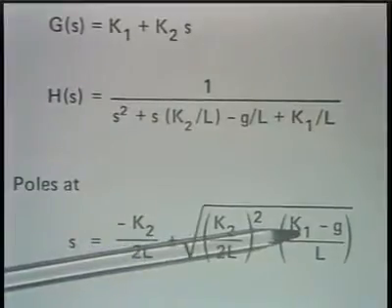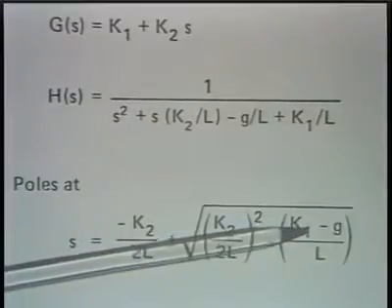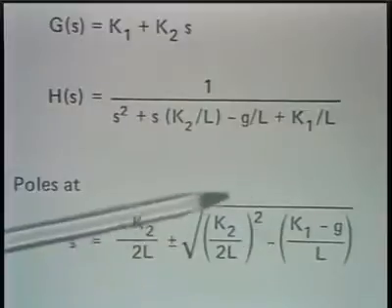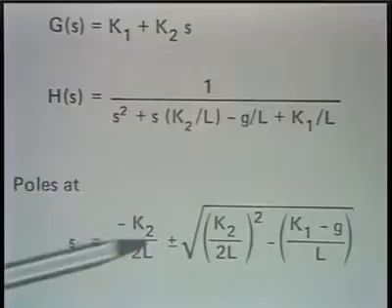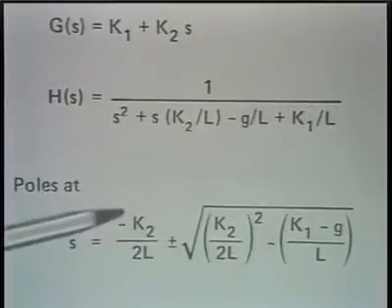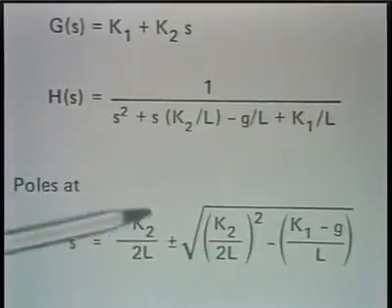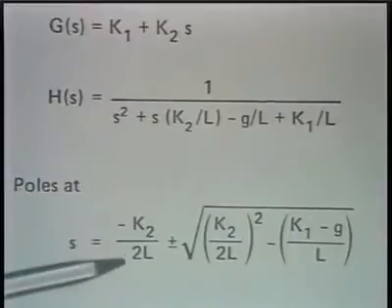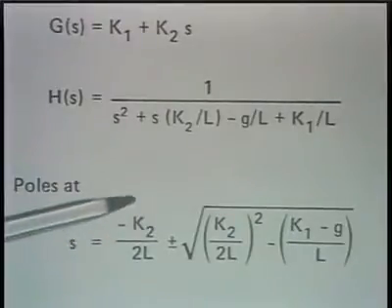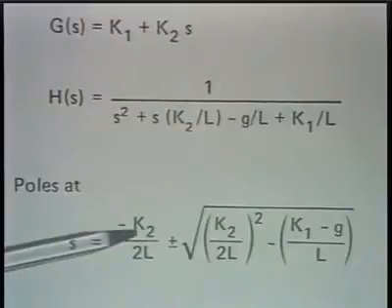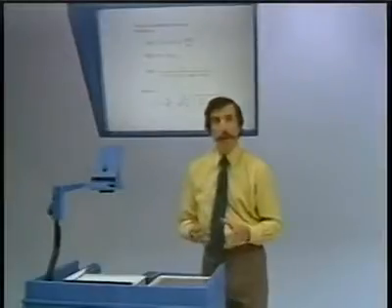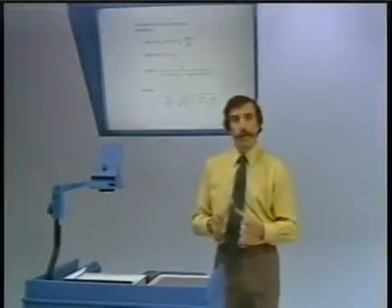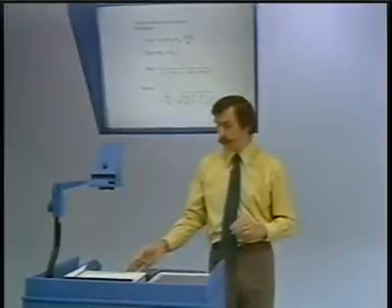And we'll first of all examine this with just k2 positive, because what we can see is that as we vary k1, if k2 were negative, that would more or less immediately put poles into the right half plane, and the more negative k2 got, the larger this term is going to get. So in fact, as it will turn out, we can stabilize the system, provided that we choose k2 to be greater than 0.